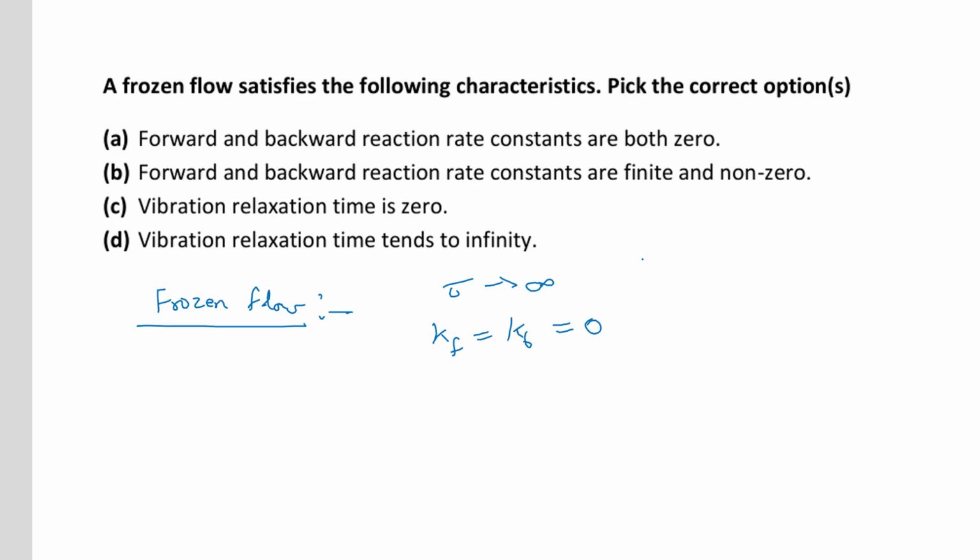Or it can be said like this, that flow is so fast that chemical reaction does not get time to happen. So in this problem, answer will be option A, where both forward and backward reaction rate constants are 0 and vibration relaxation time tends to infinity.